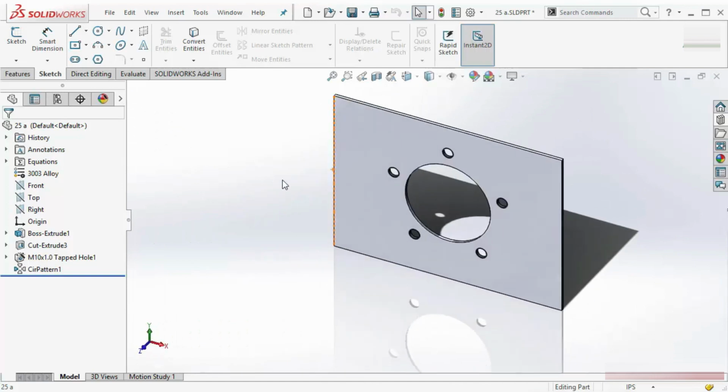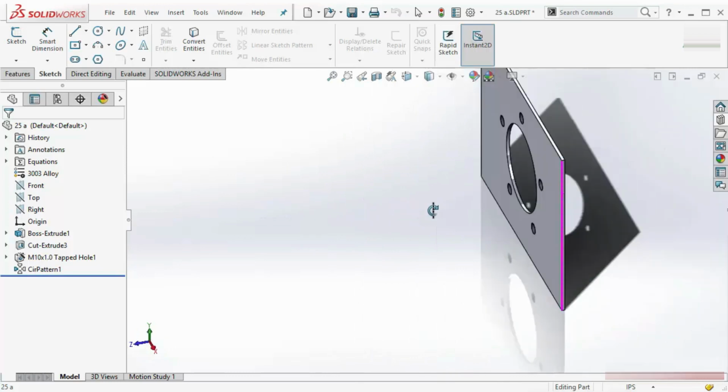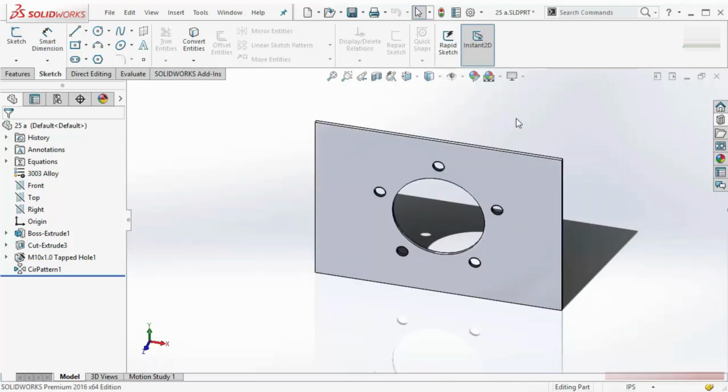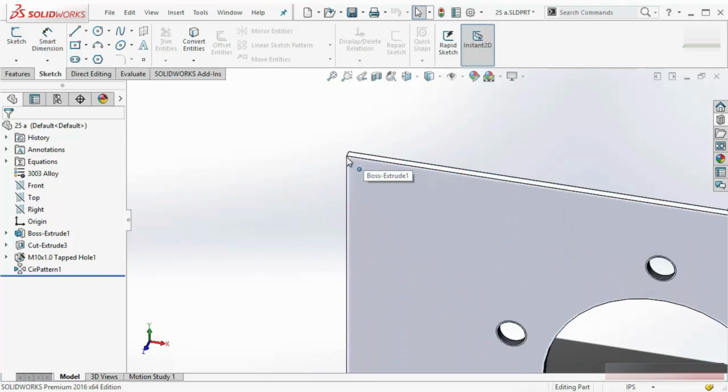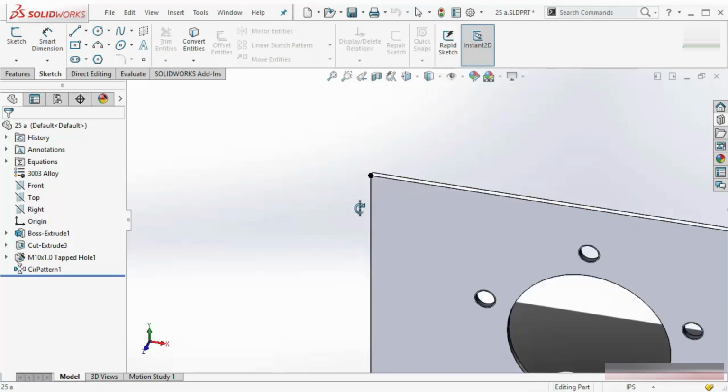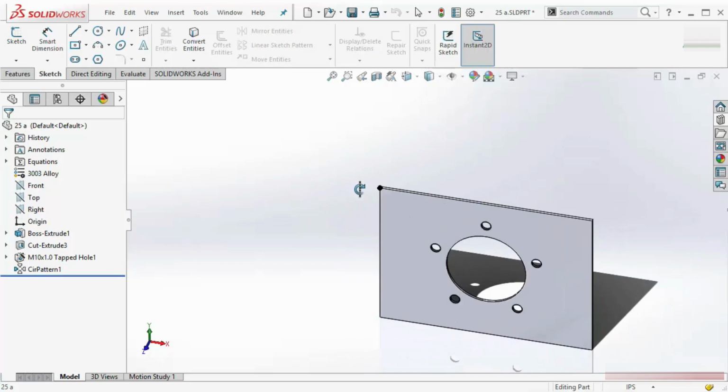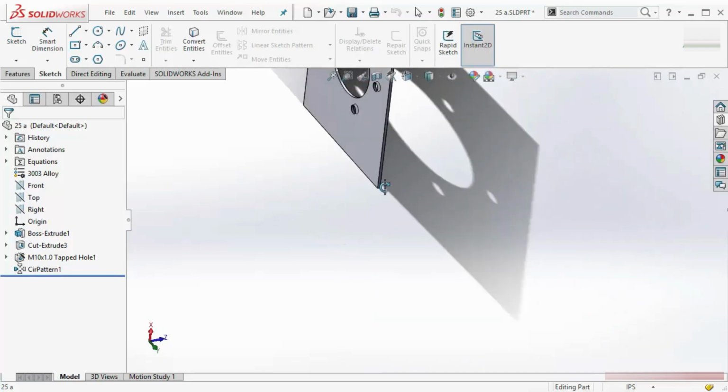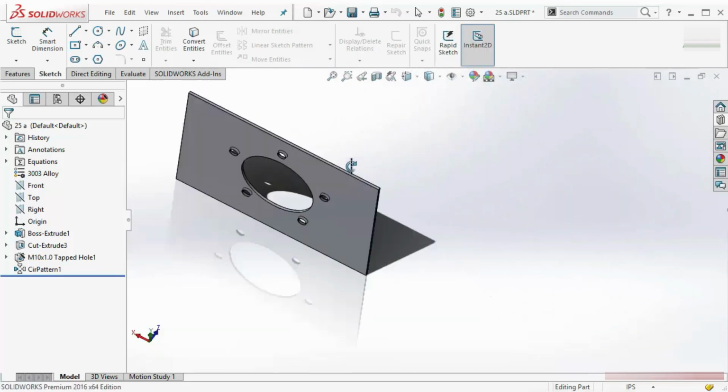I am doing it again. Now I will select this line, press one time. Now this is active. Now press and hold the middle mouse button again. You can do the same thing for any point also. Let's say you want to rotate based on any point. So if I select this point, next to the cursor it is showing points. Now I have to press the middle mouse button one time, and this is active now. Now if I try to rotate it, it will rotate based on that point. This point is not moving, everything else is moving.